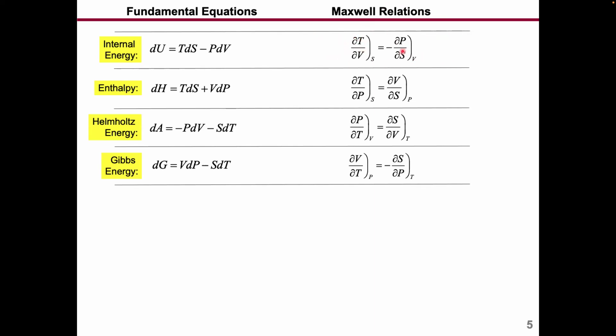This Maxwell relation is directly derived from the internal energy differential equation. Similarly, we can get another Maxwell relation from the enthalpy equation: (∂T/∂P) holding S constant is equal to (∂V/∂S) holding P constant.